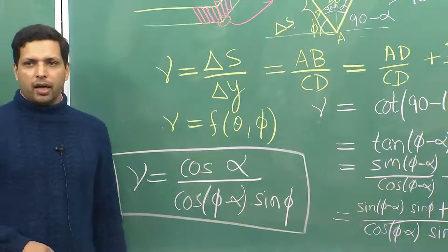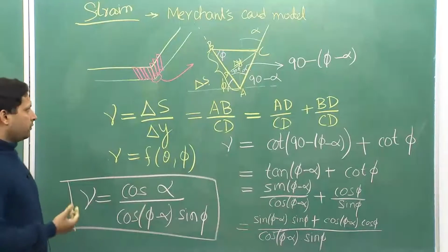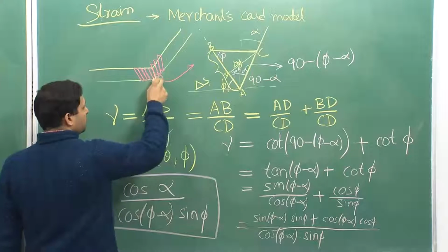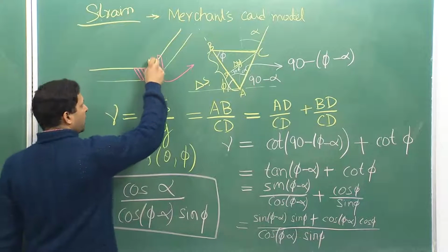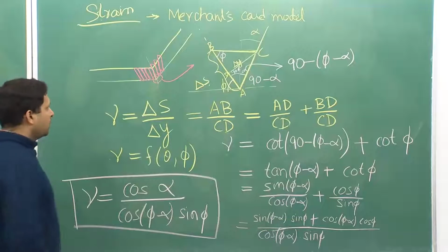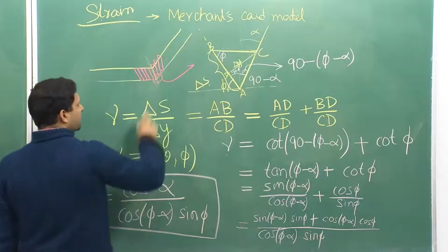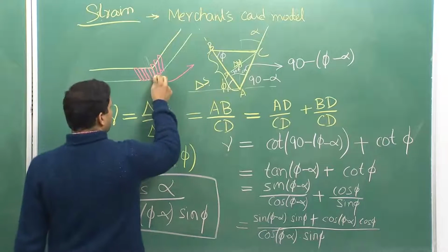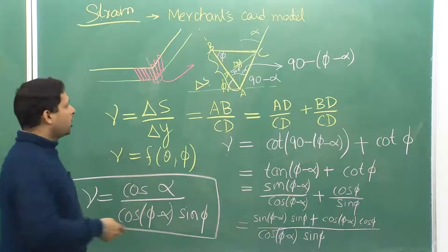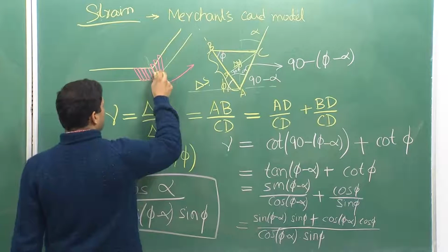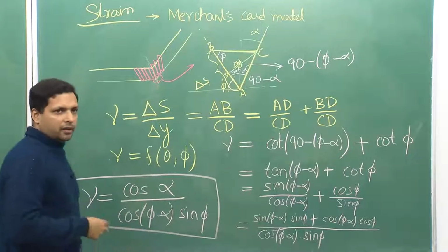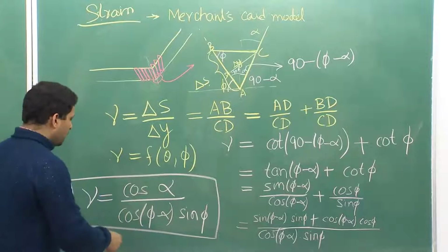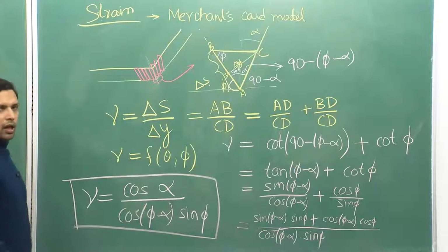We can use this to find the total amount of strain that is being imposed when the chip is coming out. So, in the chip, this is the amount of strain that has been imposed when you deform it along this line. So, we have assumed that all the deformation is taking place along this line, that is our assumed deformation field, and because of that and taking this card model, we see that the cards are getting stacked, which means they are getting displaced, which is the deformation, and that displacement or deformation is given by this shear strain that is over here.